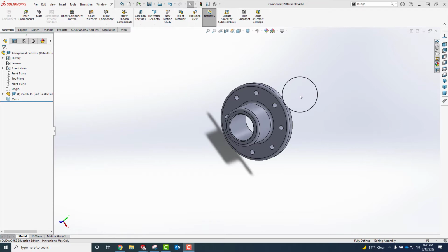In the last video we covered how to find common hardware or manufacturer-specific models using sites such as McMaster-Carr or the manufacturer of the product you're working with. Now we're going to look at what we do when we have a common piece of hardware that's used multiple times within an assembly. Hopefully that sounds like a pattern to you. If you think back to parts, we had both sketch patterns and feature patterns. And now, as we move up the assembly chain, within assemblies we have component patterns.